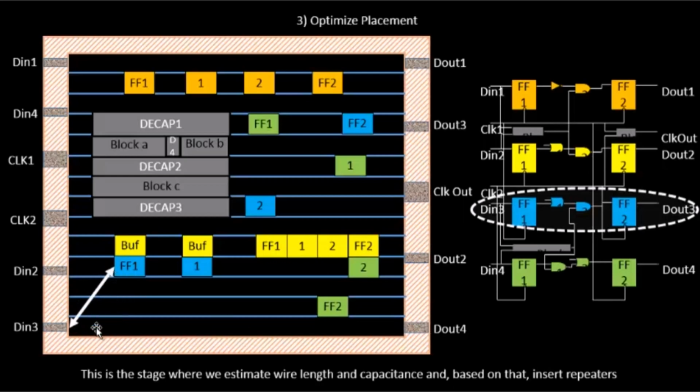These conditions are calculated based on the transition value, or the slew value, which we'll talk about once we finish the optimized placement. Basically, once we move into timing analysis for ideal clocks, we'll talk about what is the acceptable marginal condition for the signal to be considered a real signal, or a sufficient signal to trigger flip-flop 1. We'll talk about that.